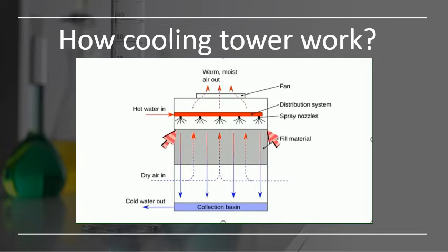Simultaneously, air is sucked through the air inlet louver, causing the water to evaporate. Next, the heat in the makeup water is eliminated via evaporation. The heated air naturally rises and escapes from the tower. The overall process is carried out in adiabatic operation.